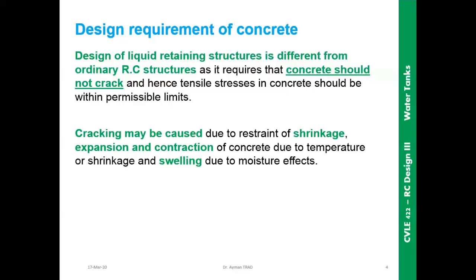Of course we know this information, that concrete is subjected at early age to the shrinkage phenomena. Why does shrinkage happen? Because to ensure a workable concrete we have to place more water in the mix than necessary to ensure the hydration process. So this water in excess will evaporate within time. There is no need to recall that shrinkage is a time dependent phenomenon which will reach an asymptote after 5 years. During these 5 years it is shrinking, it is contracting. Why contraction? Because the water inside will evaporate, meaning the volume of the concrete will be reduced, so we will have contraction.